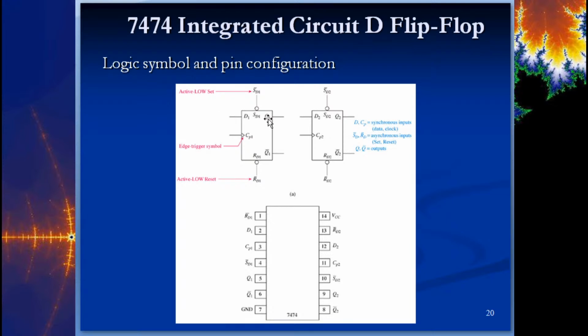That's going to pass right through to Q and cause errors. If you're just accepting D in on the edge, whether you're going from high to low or whether the clock pulse goes from low to high, you're only taking it at that one point in time. So you're much less susceptible to getting some noise on the line and causing an errant high that you don't want.